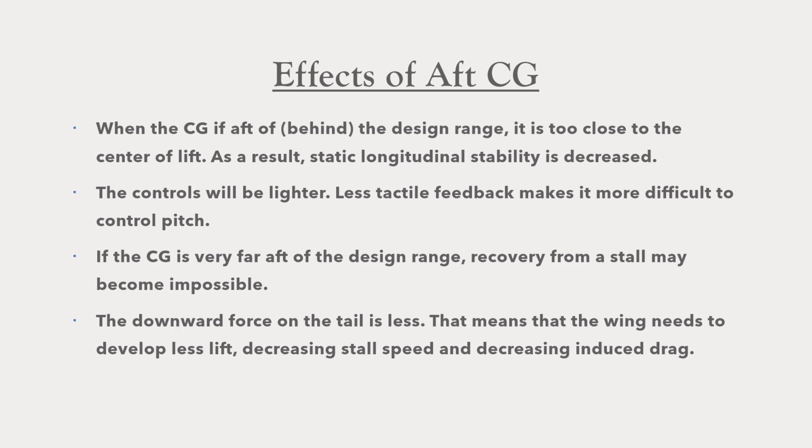With the center of gravity further back, the amount of downward force on the tail decreases. So that has the beneficial effect of reducing the amount of lift that the wing needs to produce, because recall that the wing needs to produce lift both to counteract weight and to counteract that tail force. So decreasing the amount of lift that the wing needs to produce will decrease the induced drag, and it will also decrease the stall speed and improve the cruise performance.